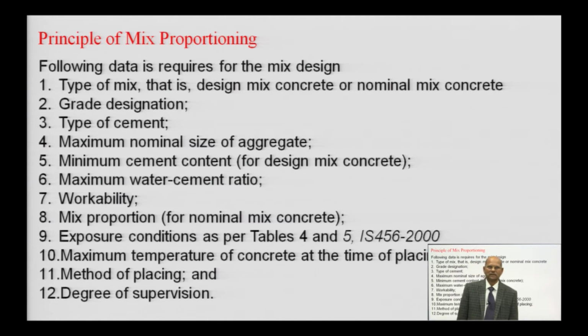Then we have exposure condition. As per tables 4 and 5 of IS 456, the exposure conditions are restricted. What should be the maximum or minimum condition? What should be the maximum water cement ratio and minimum amount of cement, and another is the maximum temperature of concrete at the time of placement. That is also important. We can't go on placing the concrete if the temperature is more than 40 degrees centigrade.